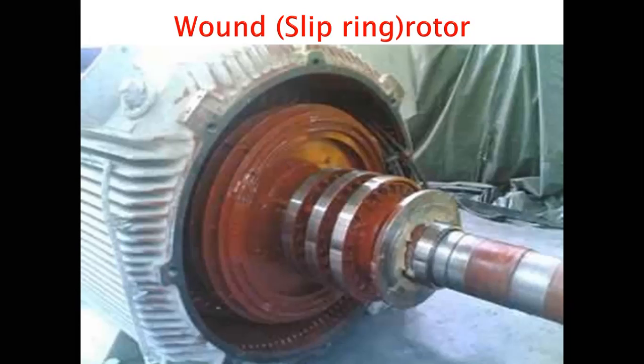So here, if we are using the slip ring on the same shaft as the rotor, at that time you will get higher slip, and as you get the higher slip, you will get higher torque. So if we talk about the advantages of the slip ring induction motor, it will have higher starting torque, and there will be a requirement of low starting current. So we can say these are the advantages of the slip ring induction motor.